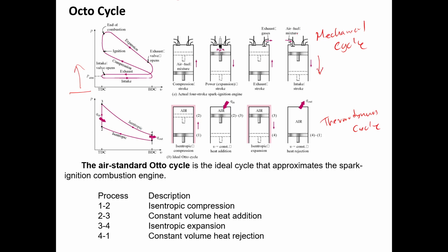Now what happens when the piston goes down? It creates a vacuum, right? Now you are opening this port to atmosphere. So in atmosphere you have 1 atm, and you are opening the cylinder chamber to atmosphere. That means you have 1 atm in here at the beginning of the intake stroke, right?